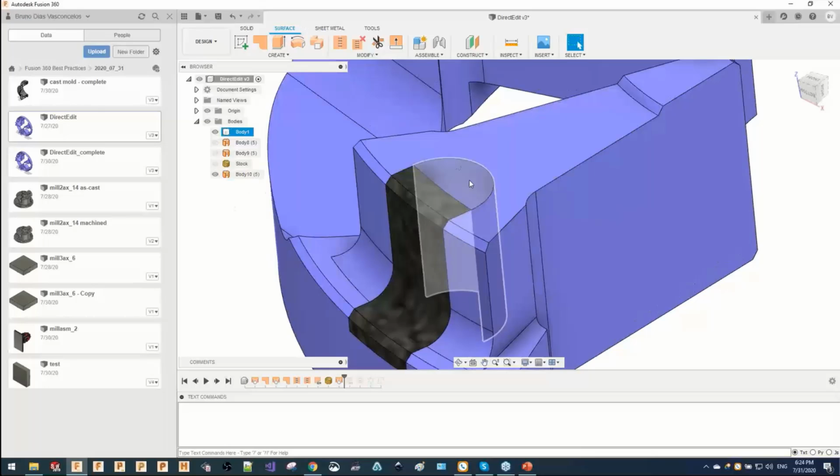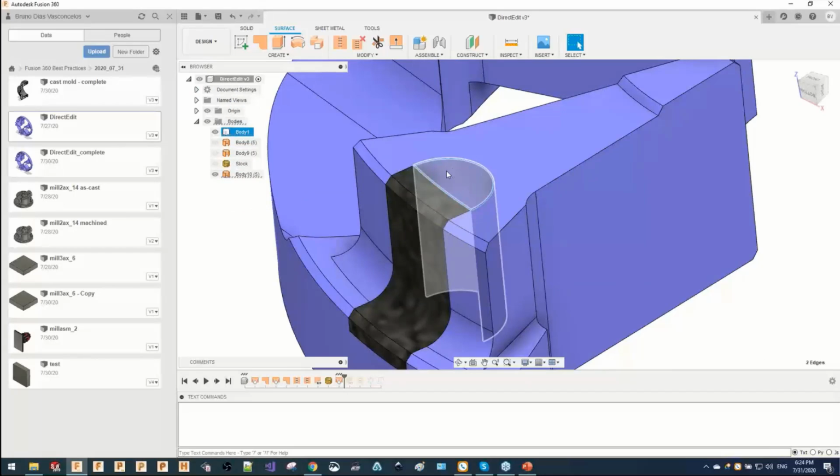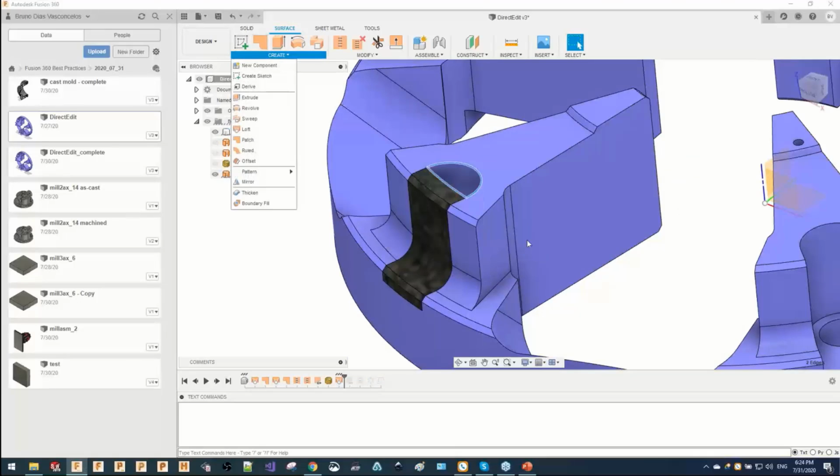And then I'm going to cap this area over here. The tool is not diving there anyway, but I prefer to have a surface right on top of that region, so I just ensure that I don't have any tools going there by accident, because I'm going to drill that with a drill bit.